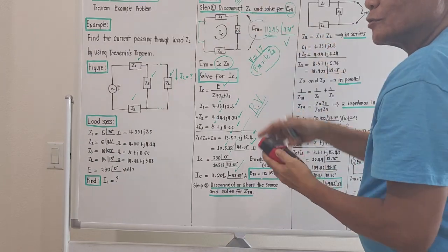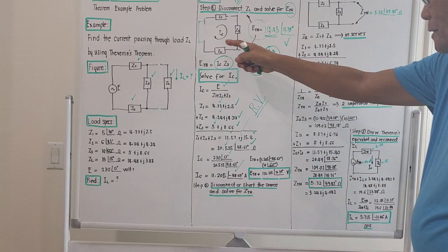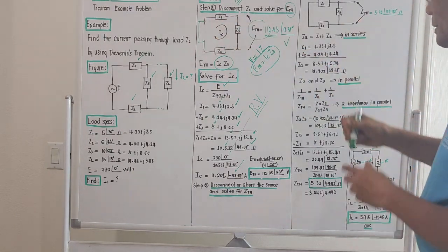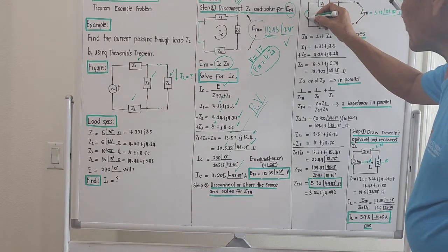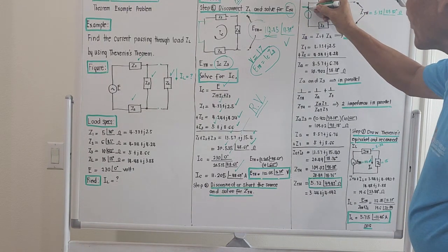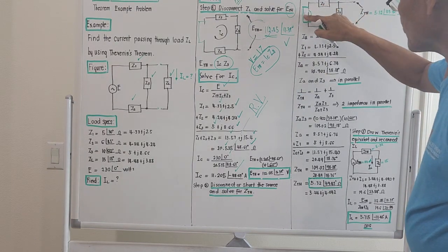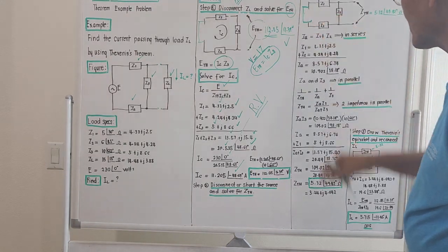But under Thevenin's theorem, if we are on the blackboard, okay, after the disconnection or shorting out of the voltage source, the diagram will be something like this, right? There was this voltage source initially, but under step number 2, we short it out to compute for ZTH. We short it out, so there's a short over here, no more power source, right?